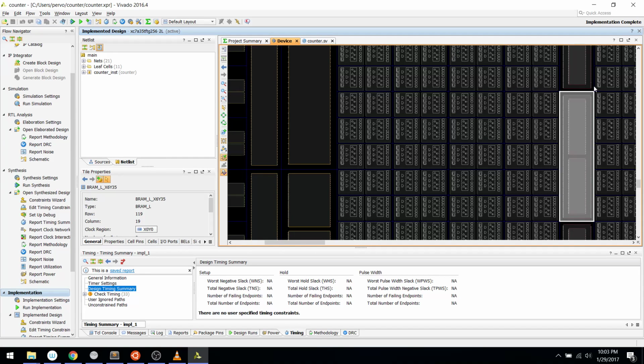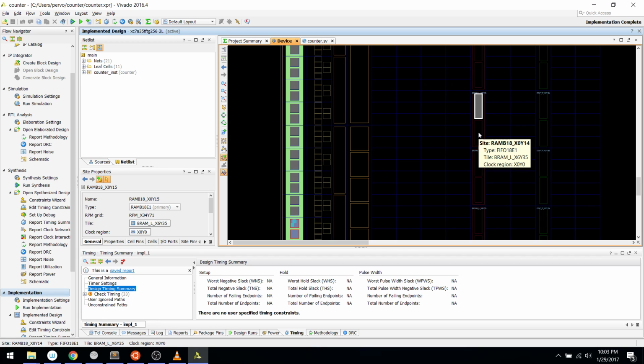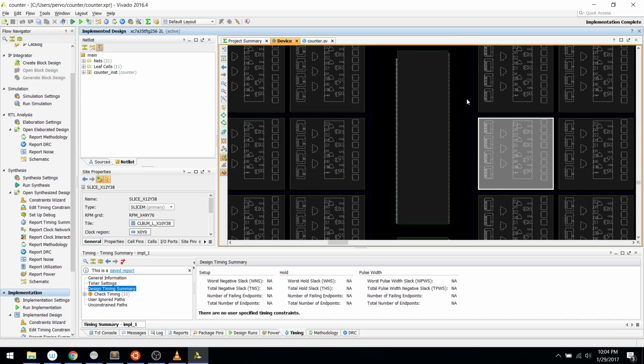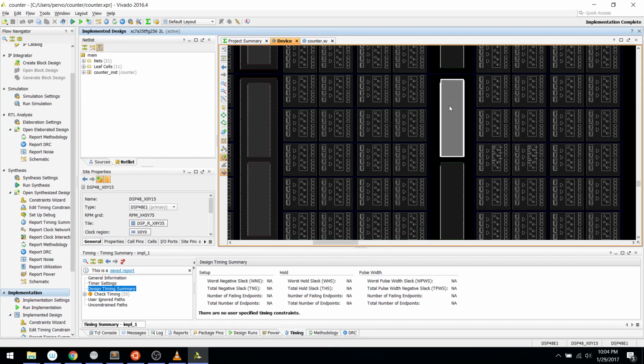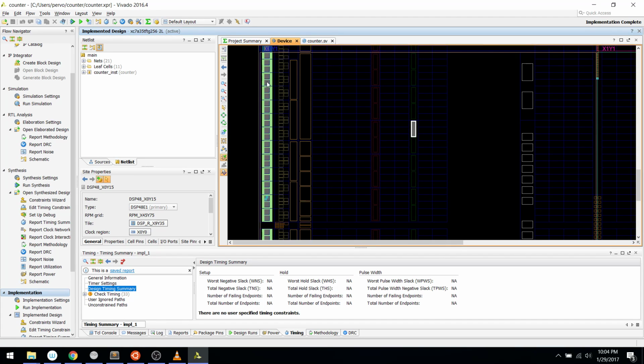Beyond that, there's a bunch of other resources on this chip. The big ones are these so-called BRAMs, block RAMs, which are a fast SRAM. I don't know how much BRAM this thing has on chip, but it's quite common for these things to have a few megabytes of SRAM, or BRAM as it's called, on the die. You can see the red ones over here, and over here you have another fixed function block. It has the same basic footprint, at least in the schematic view, but it's not BRAM, it's actually DSP, so this is a 48-bit multiplier, a hard-coded multiplier, so you don't have to implement that yourself out of LUTs and carry chains. Aside from that, there's a bunch of stuff with I/O buffers and FIFOs for dealing with I/O and all this other stuff over here.